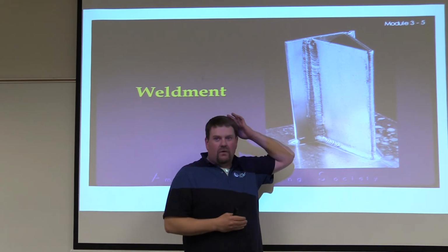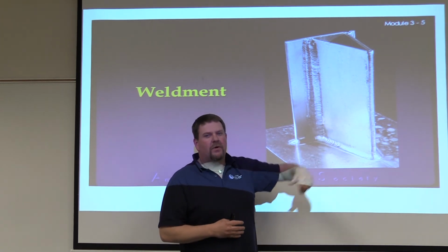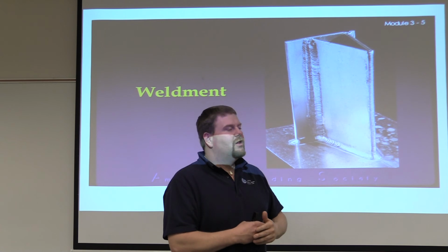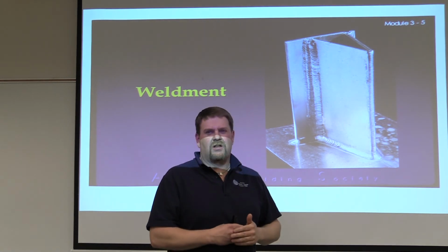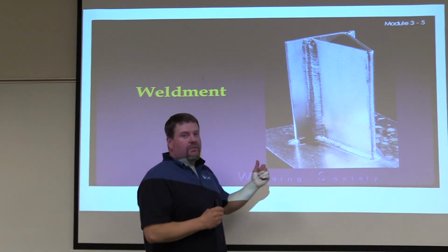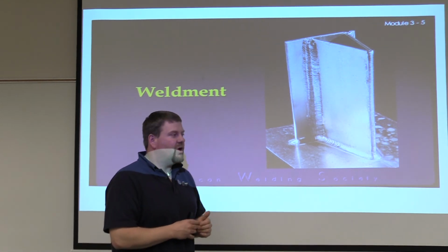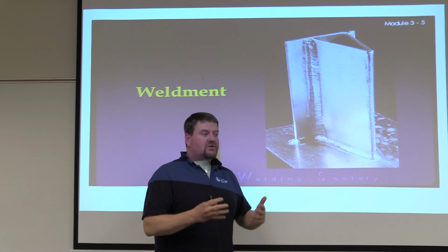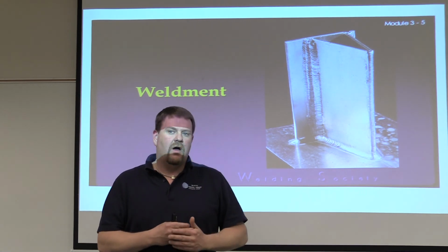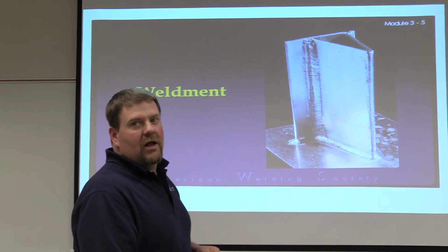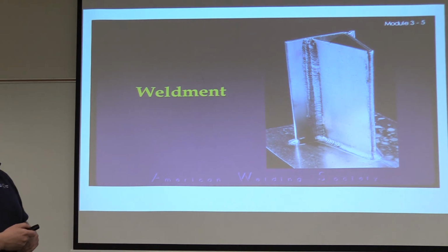I've seen them do two parts of the pipe in an uphill manner. They think they got me tricked. They'll come back in and try to put the hard piece in a downhill fashion. Doesn't happen, they failed immediately. We've had to cut pieces out on very expensive projects because it didn't follow the procedure. It's no longer insurable if you do not follow the procedure, okay? That's an important part of this whole situation.